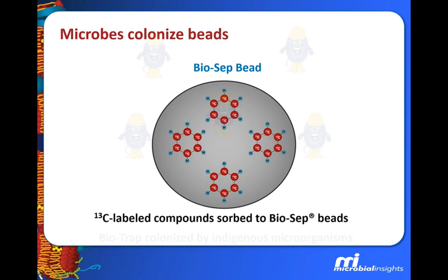But I'd like to stress that there's more than activated carbon adsorption going on here. Because of the pore size distribution, there are two forces holding that compound inside the bead. One is the adsorptive properties of the powdered activated carbon, but the other is simply the mass transfer resistances that exist when this compound gets adsorbed deep into those pores.